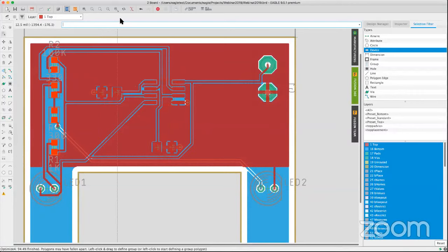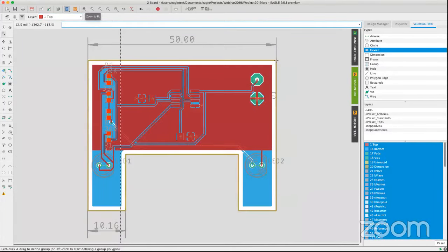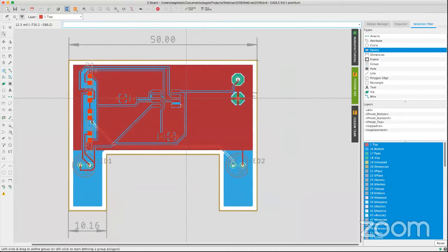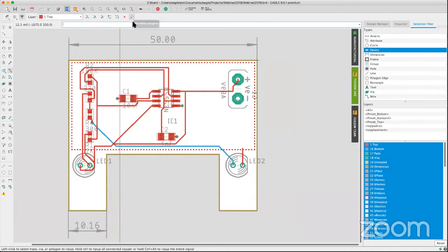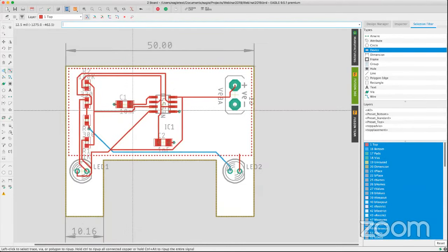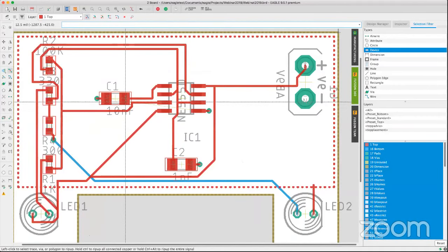Okay. Now that I've selected the job that I actually wanted to look at, let's take a look at what's going on here. So it's actually routed 100%. Actually doesn't look that bad. Looks actually nice and clean. We could get rid of the polygons, that way we could take a better look at how it routed the board. And as you could see, this air wire is only there just because the polygons are not poured. Okay, that's why. That's a ground connection.